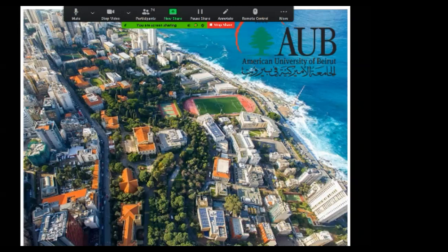Well, again, the top layer, the surface layer, is still important. We tried the Boeing 777, and that 777 is the heaviest aircraft that lands there. So we saw that, yeah, huge impact, but you might still have smaller gears, smaller aircraft where stresses are going to be extremely high on the surface layer as well. So you cannot neglect the surface completely. I think both should be made of high quality. Don't underestimate the shear stresses at the top of the pavement, of the surface. So we can't neglect them. Both are as important.